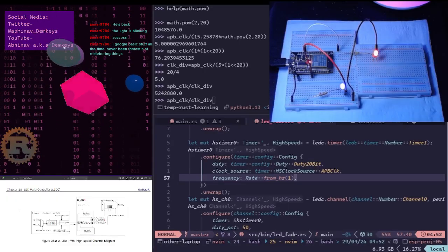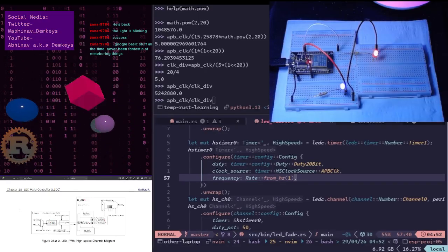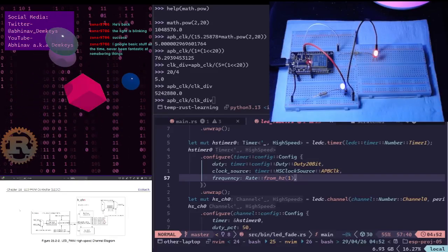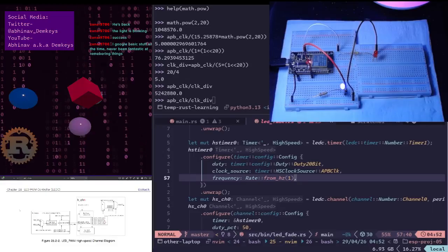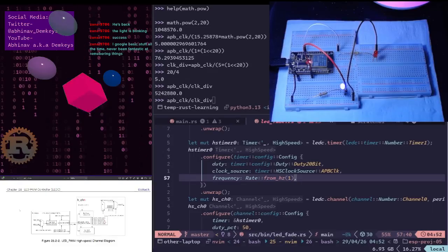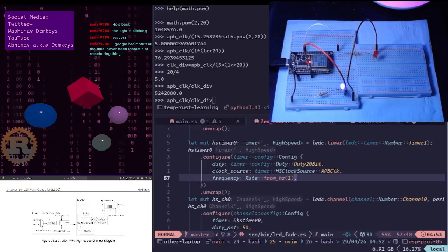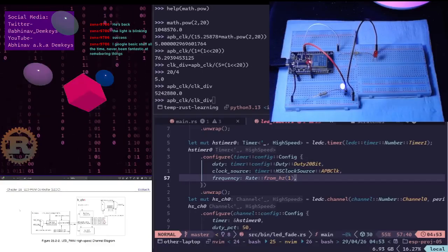It can't actually pulse halfway through a clock cycle. Instead, it alternates the integer division. To get 10.5, it will divide by 10 for one cycle and 11 for the next cycle. Over time, the average frequency is exactly what you requested. That's interesting.